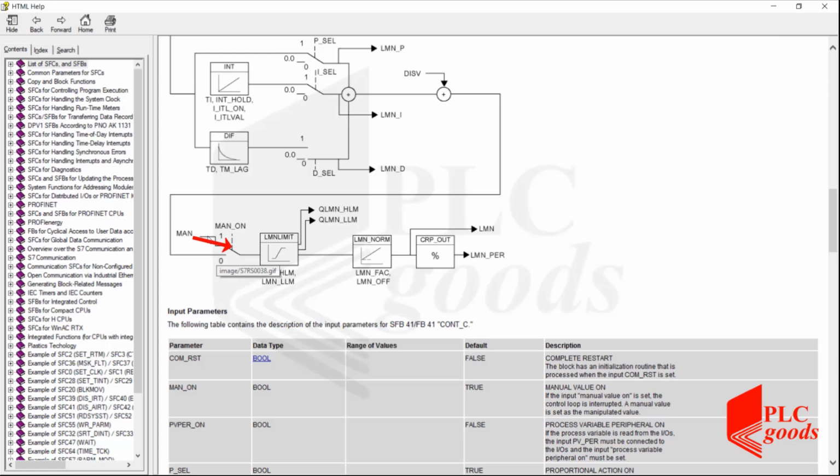For example, I can connect the man input to a potentiometer to control the inlet valve manually. Remember, my current program already included a program to control the inlet valve manually with a potentiometer. But I want to control the inlet valve by using my proportional controller's output.